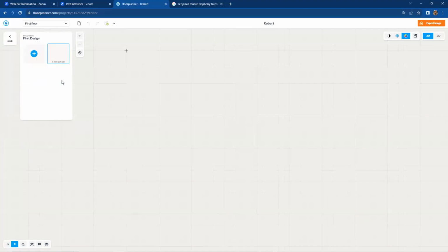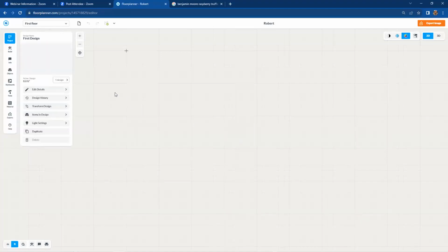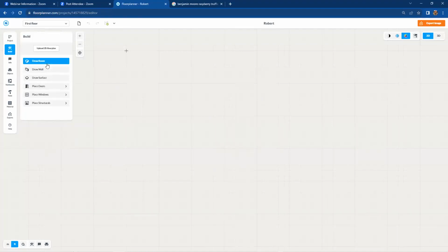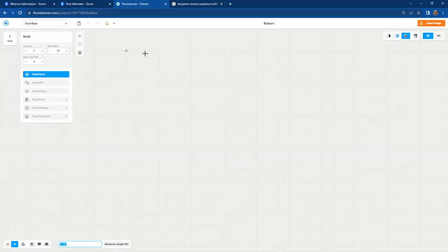Cool. Go to the Designs tab. There's my first design. Here it is. Zoom extents. There's nothing there. I'd say we're doing pretty well. We now have an empty plan, which was the whole intention of getting us to this point. Now let's go ahead and build something. So if we go to the hammer for construction over here and say draw a room, which is our simplest way to go from one corner to another corner, 4 walls, ceiling and floor all at one time. It wants to know how thick your walls are, of course.